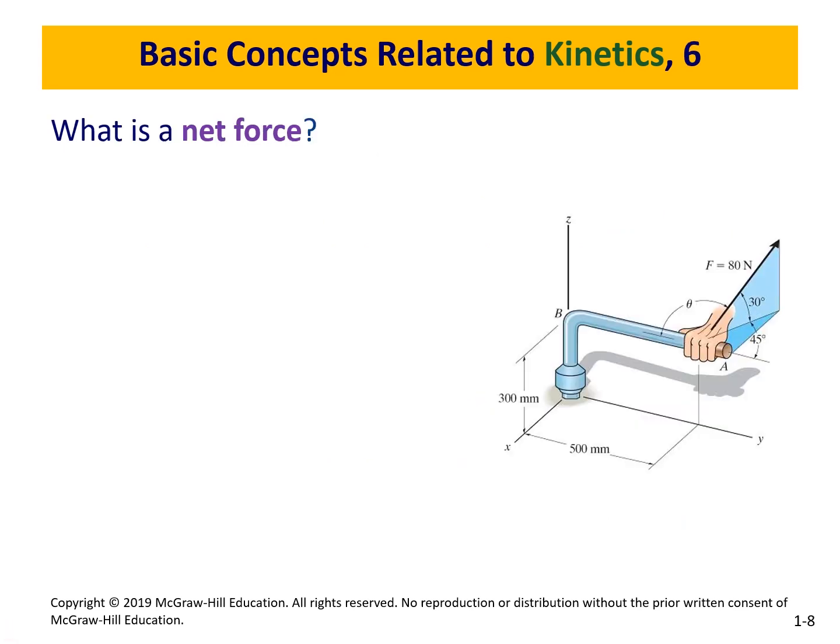Now, do you remember the names of the angles we use to analyze static systems? How many types of angles do we have? What do you call these shaded angles? Those are called projection angles. We have another type of angles. Do you remember the coordinate angles? It's the angle between the line of action of the force and one of the coordinate axes, X or Y or Z. So we have two types of angles. Anything shaded is a projection angle.